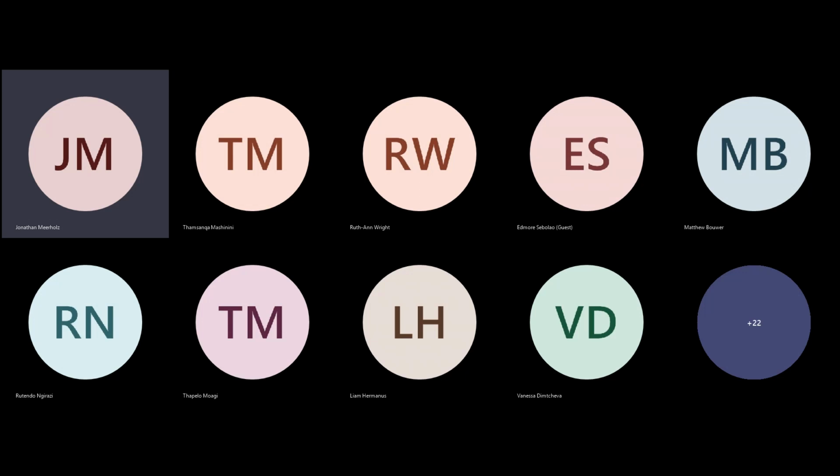But for phase velocity, you're timesing the two, and that has to be per length, because the product of the per length capacitance times per length inductance is different than total inductance times total capacitance, if you understand what I'm saying.